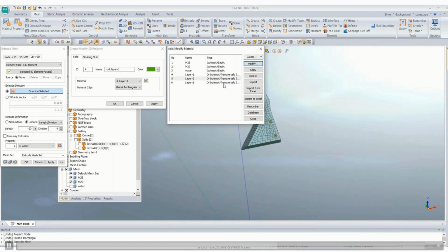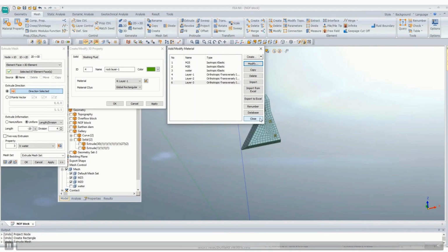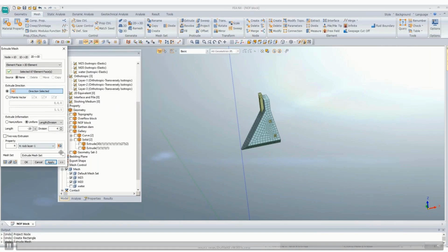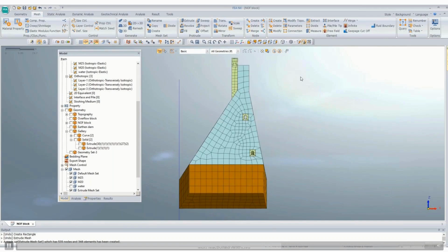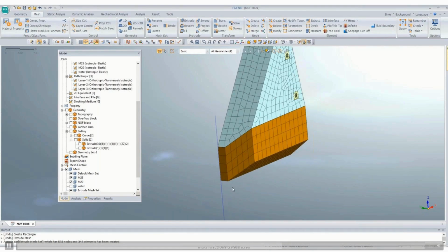Then layer 3. I'll consider only 3 layers here. Say 5, then say 12, whatever. These are all assumed parameters. Okay, rock layer 1, let me check this. It is okay. Now probably I can align these nodes at this plane, so I'll change my work plane.